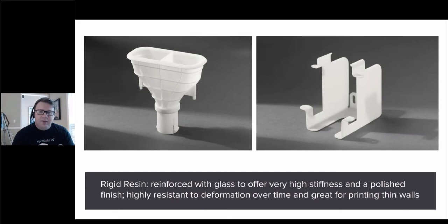It doesn't deform at all. It's insanely rigid, and it's got a really nice ting to it because of that glass fill. The finish is really incredibly smooth too. This material is quickly becoming one of my favorite materials for anything that needs to resist any sort of deflection. You don't want to try to bend this material at all because it will crack instead of deflect. So really good for that. Also really good for anything that needs to hold its geometry over time and not deform.